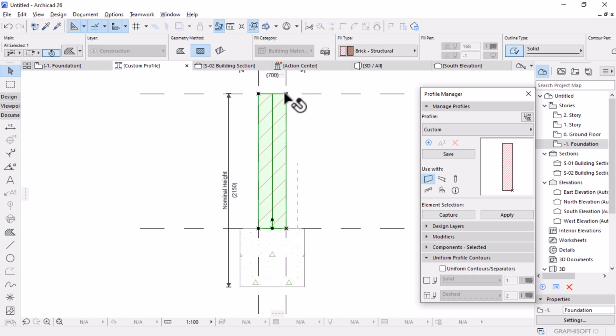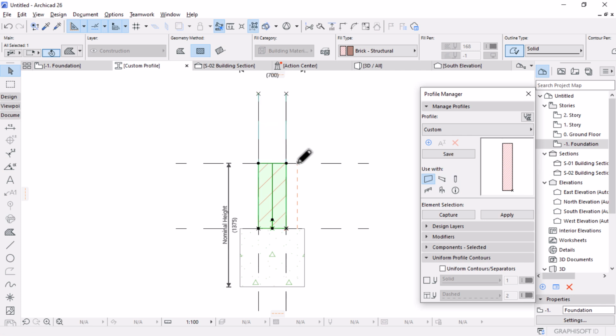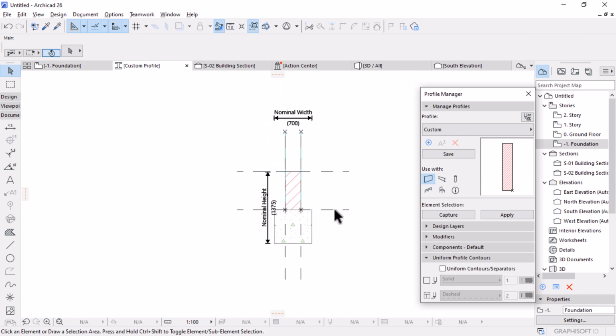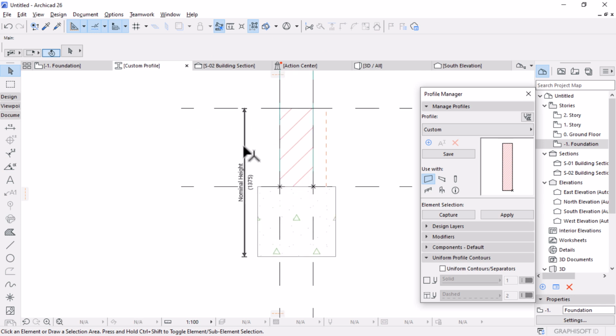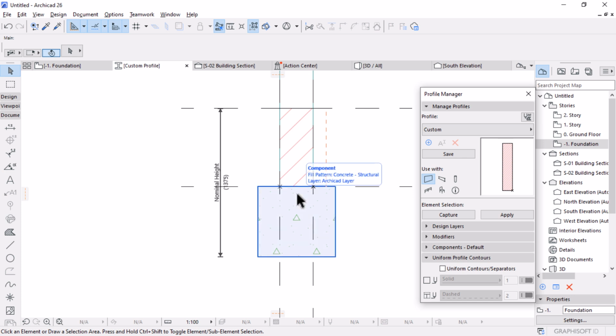That's where our wall height is supposed to be. So I'll select this wall and then pick this edge to offset the edge to our 725 dimension. That's basically what we have in terms of our footing. It's going to be like that. In terms of the profile, we would rather take care of the pen sets. It's very advisable to do that.